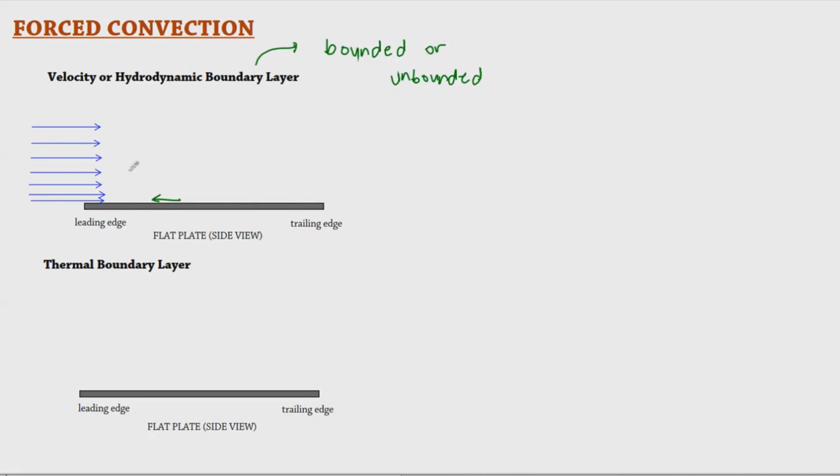So in this case, if we would represent this as vector arrows, the longer the arrow would be, the greater the velocity would be. So if we would be representing that, we could say that this would be extending further. So imagine these fluid layers. The higher you move away from the boundary, the less they are resisted, because the flat plate would be resisting those that are very near its boundary.